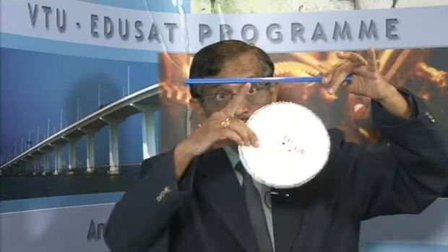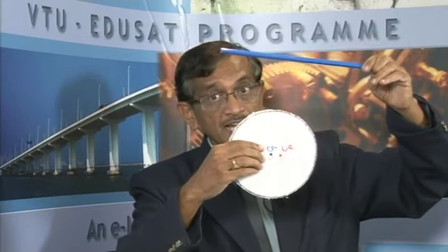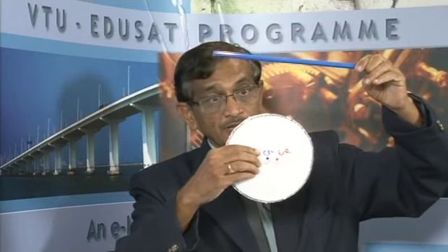Hc, I would like to know where the center of pressure is. The value here is 1.5 plus, this is 2.5, the diameter. From here to here, I will take half of that. What is the value? 1.25. So 1.25 plus 1.5, how much will that be? 1.25 plus this top 1.5, this will be 2.75. So we know the Hc value, we calculate the force with the help of the same formula and we go ahead.